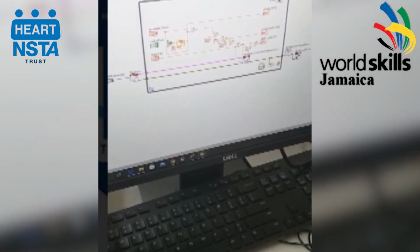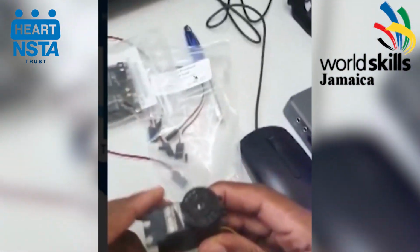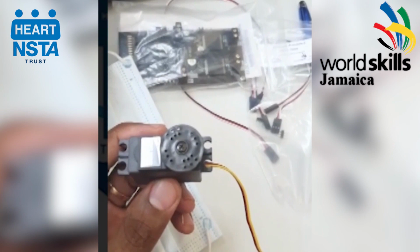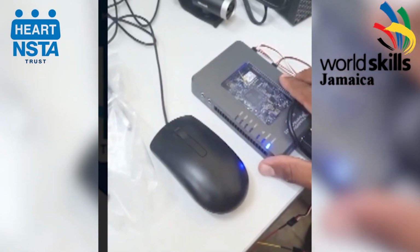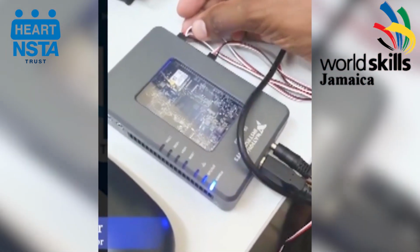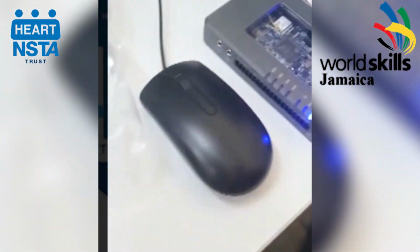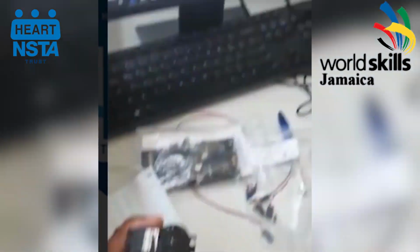Now we're using pulse width modulation. All of these components are a part of the new Industry 4.0. And these are things that we'll be using as we progress as a world, as a planet. This is my RIO from National Instruments. It has the capability to output a signal in the form of pulse width modulation. This pulse width modulation is then used to control the servo motor and to determine the direction as well.